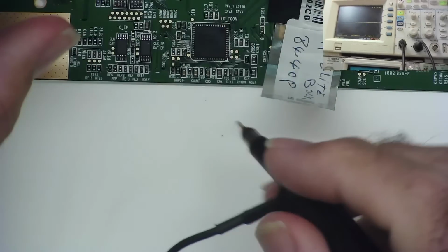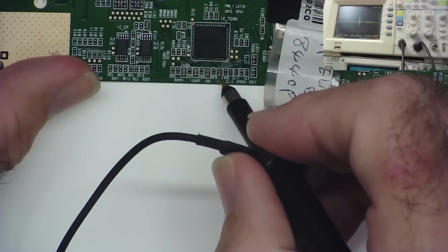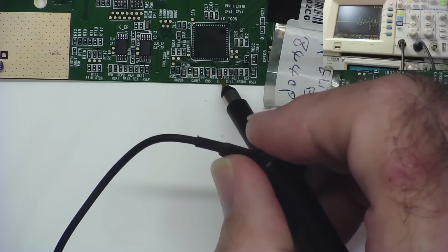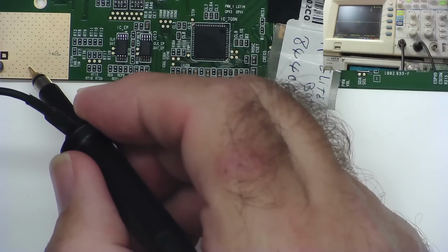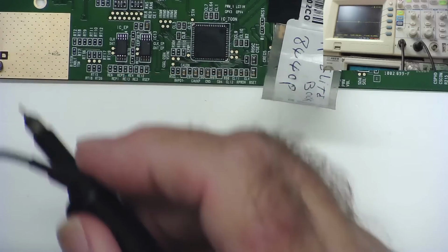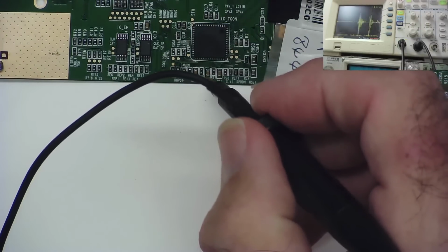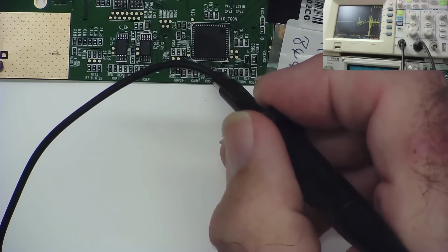Just find the oscilloscope probe. There it is. Okay, so it seems to be on these input ones. You can't see a lot because the signal is so small. I'm on 200 millivolts. I'm just picking up a lot of interference basically. Even if I connect to the ground on the laptop with the oscilloscope probe, I've got the same on the screen. So I can't really say I can see the data coming in, but again we can check for data coming out.